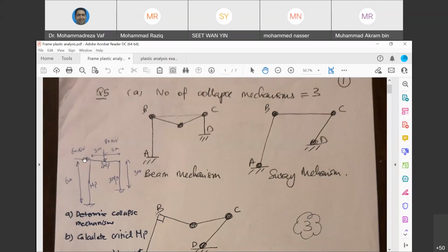So under the lateral load, the frame is going to move, and the movement at points B and C is always equal. Meaning when we apply the lateral load to this structure, the deflection that occurs laterally here, if this one is delta, this one is also going to be the same value. Both of them are always delta. This is also another point that you should know. Similarly, in the combined condition, if this one is moving delta, this one also is moving delta under the lateral load. So these are the points that you need to understand when it comes to frames.